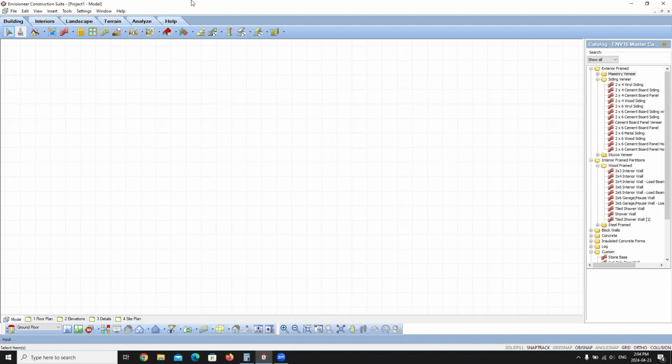Again, today's class is on remodel design, and we're going to be going through and illustrating a remodel project that involves denoting on the plan what is new, what is existing, and what will be demolished. We're also going to be discussing how to denote the various elements and to ensure that only the new construction elements appear in your material list.